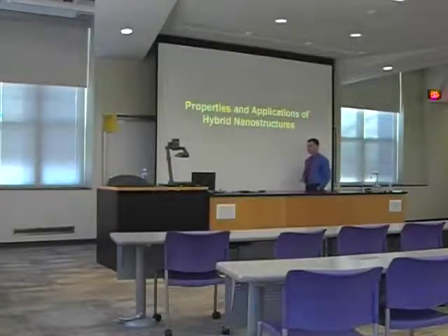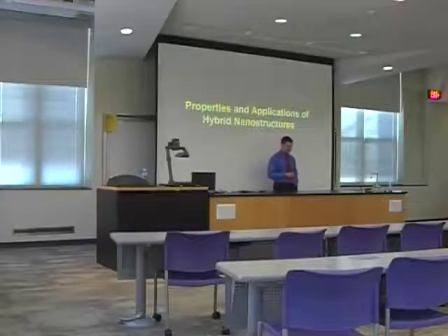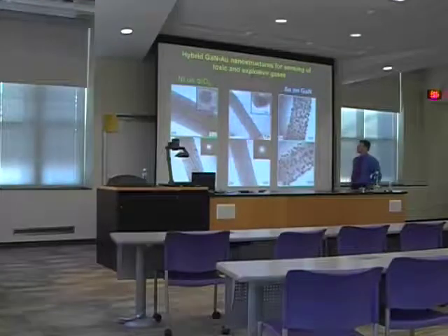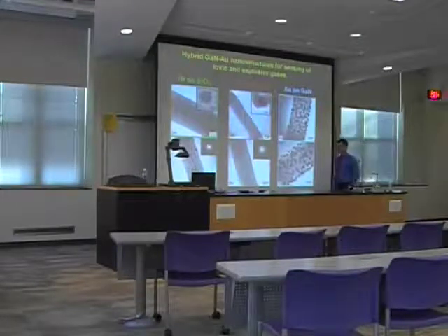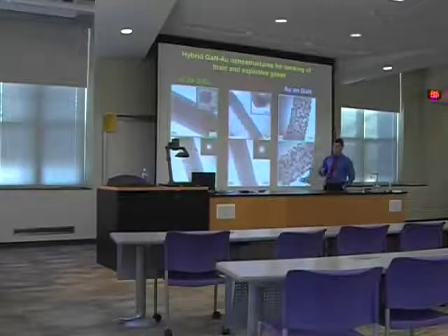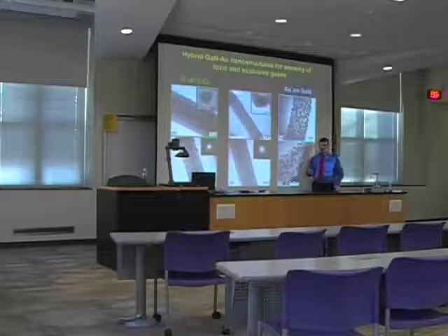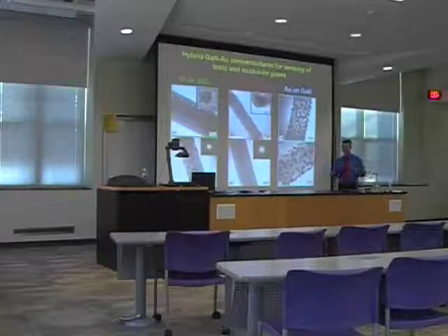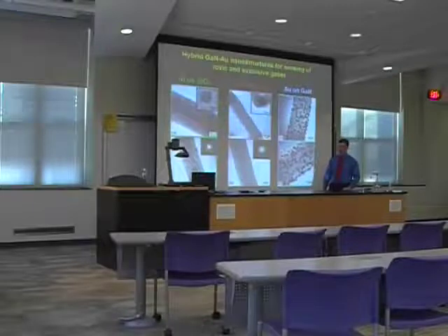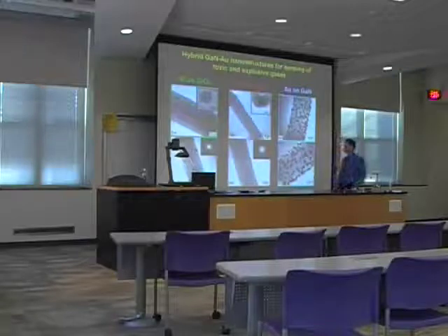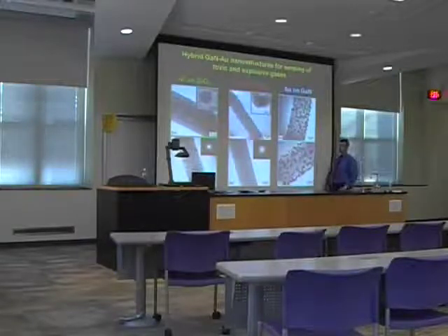Next part of my talk, again about self-assembly, slightly different nanostructures and slightly different applications. So these are examples of self-assembly of gold nanoparticles on the surface of nanowires. Generally, how nanowires are grown. This is a mat of nanowires fabricated in the standard tubular furnace under high temperature, about 900 Celsius. Normally, they're obtained by decomposition of ammonia.